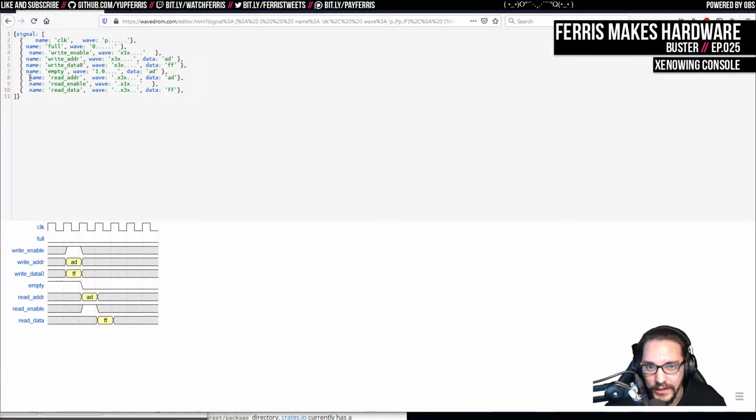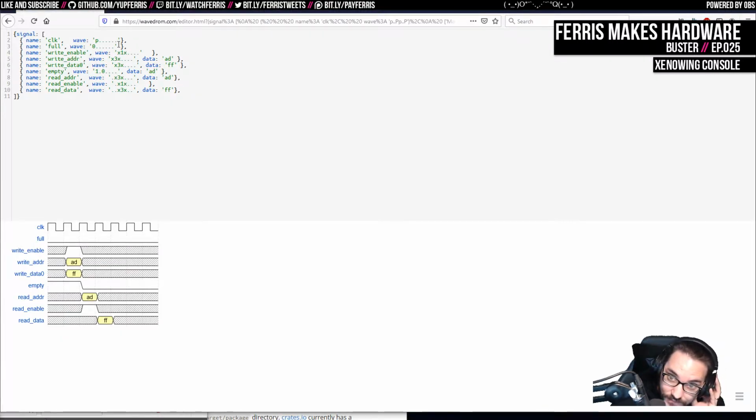And maybe it's actually better that for this FIFO interface I do export a signal for data valid, but we'll see if we actually need that. I have a feeling that might be something we want. Anyway, this is fine. But let's say instead we wanted to do a read a cycle earlier.